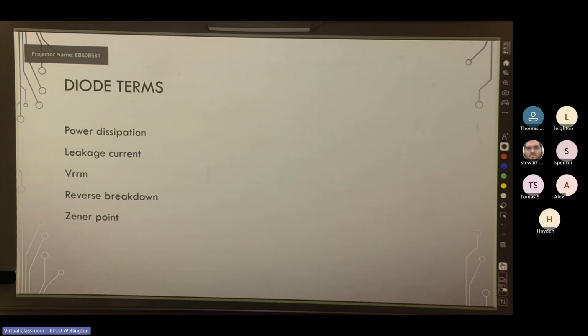So if we think about the AC supply, our maximum voltage is around 325 volts. 230 is just our RMS. So we have to make sure that the VRRM for rectification is higher than 230 volts, even if we're using a transformer, if it's being subjected to AC, so that it won't get damaged by the instantaneous reverse voltage that could be applied to it.